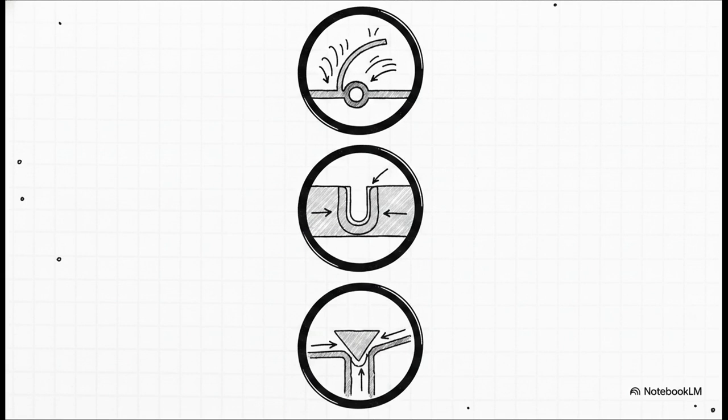In a standard shop compressor, you've got 0.2mm spring steel reed valves that slap open and shut thousands of times a minute. Over in heavy hydraulics, you'll find U-cup seals that cleverly use the fluid pressure itself to flare the seal tight against the cylinder wall. And in microscopic lab-on-a-chip medical devices, traditional mechanical valves are just way too sticky. They require trapezoidal, zero-gap PDMS silicone valves that flex flawlessly without rubbing the sides. The scale changes drastically, sure, but the fundamental job of trapping pressure remains exactly the same.